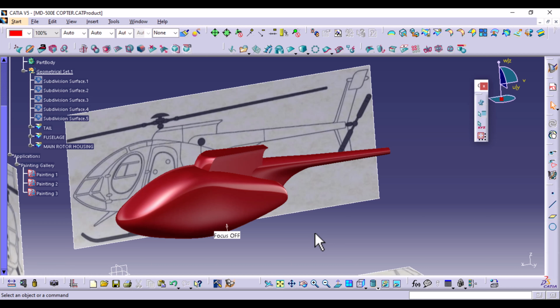So if you've come so far, you're now at par with the Class A surfacing, and we are now going to create the main rotor. We're also going to create the vertical and horizontal stabilizers, as well as this tail rotor and that stand. So we're going to use 1 aerofoil, which is used mainly for the helicopter blades, and it's also used for the tail fins, and it is the NACA 0012 airfoil. So you can head to airfoiltools.com and search for NACA 0012 airfoil.